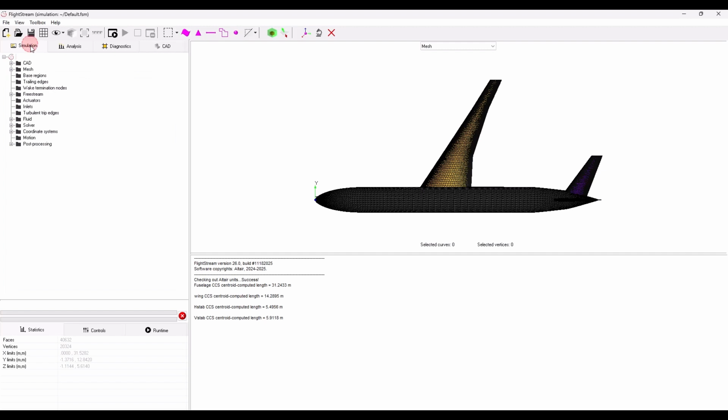The purpose of the Unite tool is to create a watertight exterior surface mesh that is suited for flow simulation. The first thing to do is to check that the surface normals for each mesh is pointing outward. We can do this by using the Green Box Info tool in the toolbar to highlight each mesh, either green if the surface normal is pointing outwards, or red if it is pointing inwards.